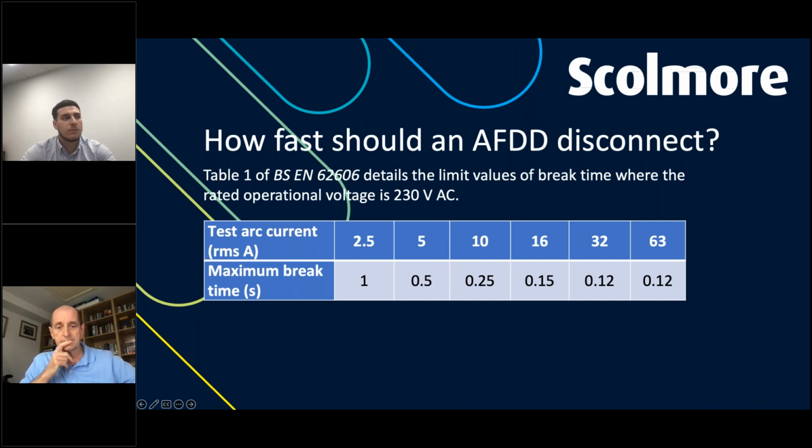So Tim, what's happening to the 1.5s and the 1 amps of the world, the lighting circuits that we would typically see? I think at those low current levels, Jake, whilst it may be theoretically possible to create an arc and sustain it, highly unlikely, the amount of energy generated by such a fault is unlikely to be able to cause a fire. And of course, Chapter 42 is to do with thermal effects and fire and the concerns that we have with that.